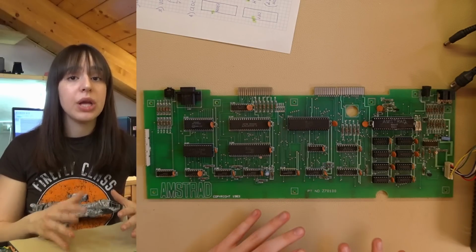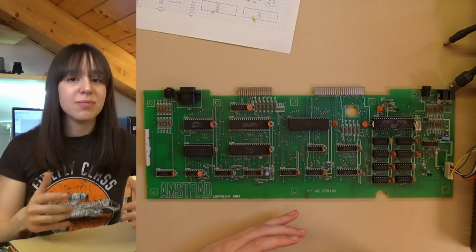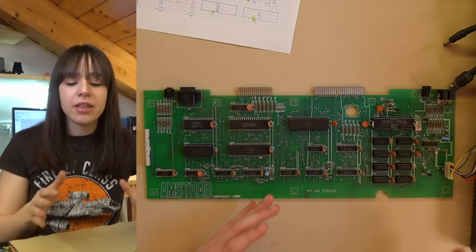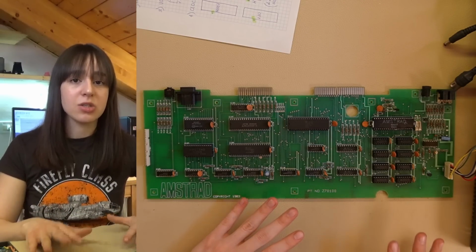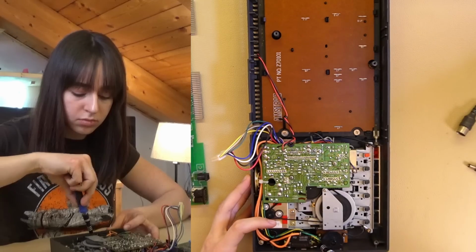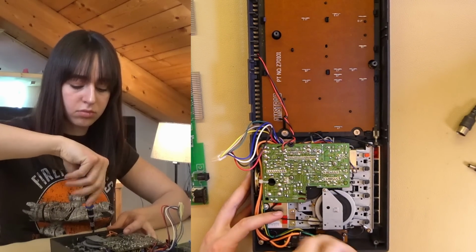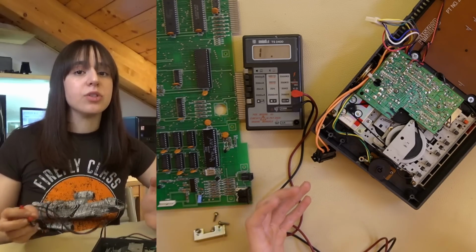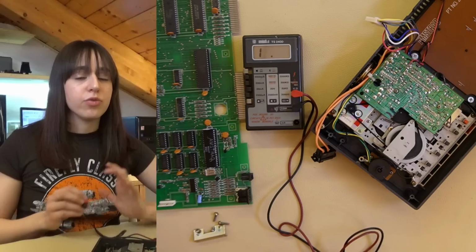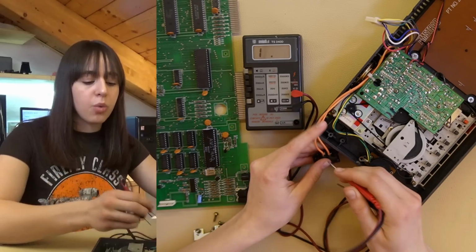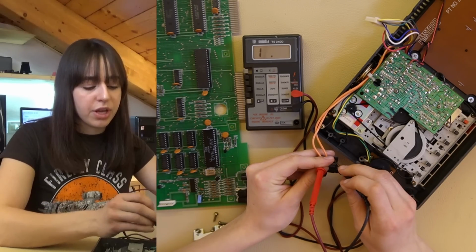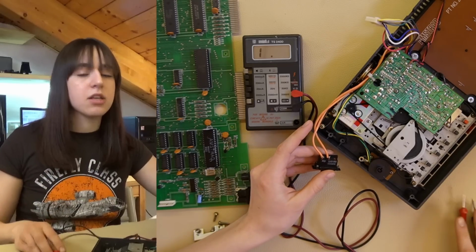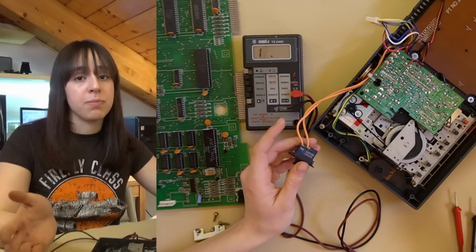At this point, it occurs to me to check the switch, and this because it could get dirty inside over time and no longer make contact. And in this case, the board was very dusty, so that could also be the problem. I'm going to test the continuity. When the switch is off, there shouldn't be any continuity, while when it's on, there should be continuity. But there's no continuity even in this case, so I'll open it to see what the problem might be.